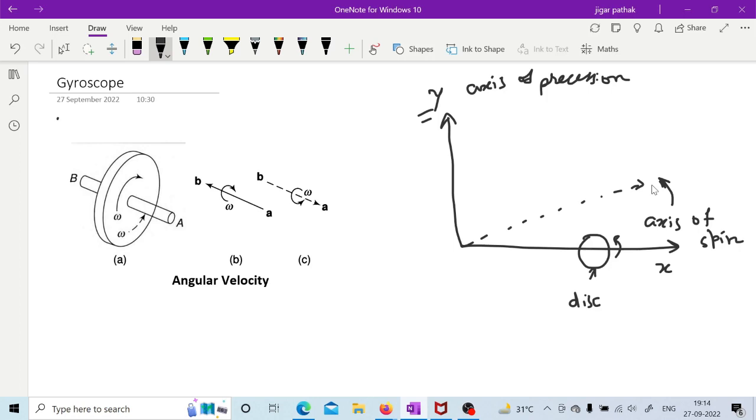That direction will be whatever this third axis is remaining, which you can consider as normal to the plane of this screen. That particular couple is known as the active gyroscopic couple, which will try to rotate that object about this third axis. And whenever an active gyroscopic couple is there in the picture, there must be a reactive gyroscopic couple also, as you have centrifugal acceleration and centripetal acceleration.